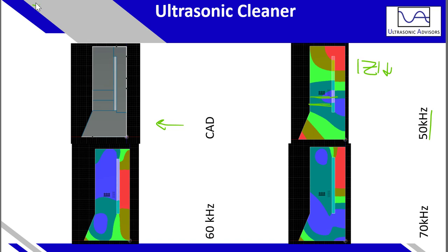Well, it's because you're driving larger velocity, larger energy in the system, which will in turn provide more internal, alternating stress on the piezo, which provides more current. And from providing more current, we get a lower impedance. This is also reflected in the electromechanical coupling factor, and we'll talk about that in the next slide.